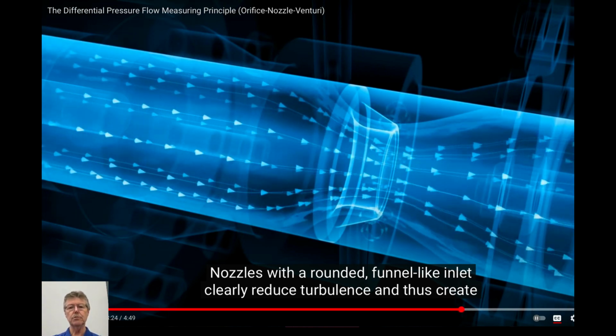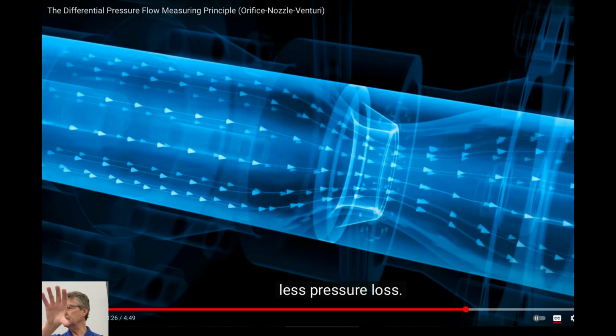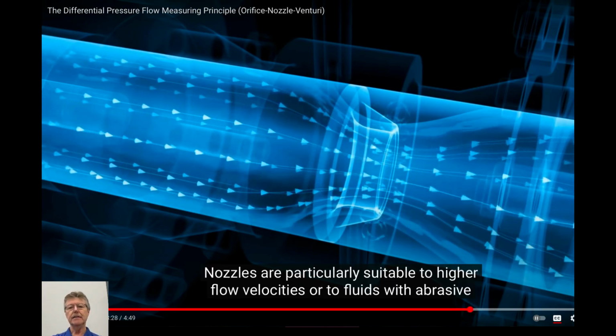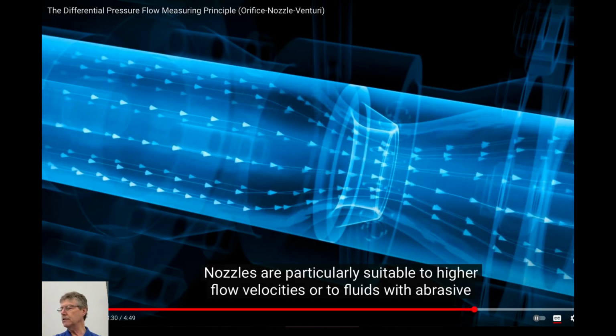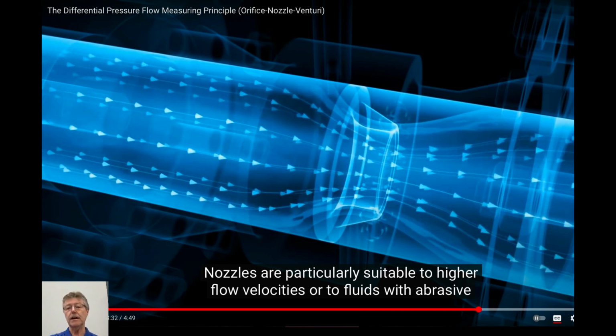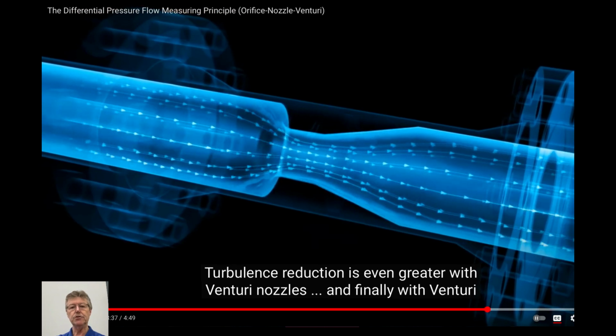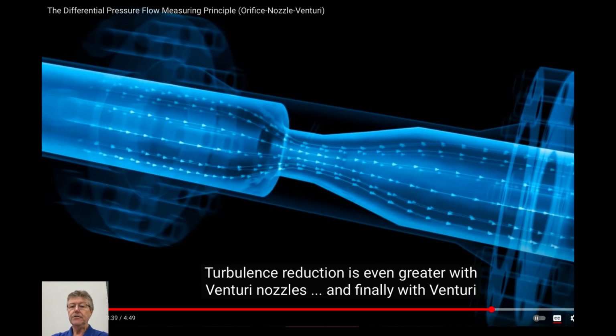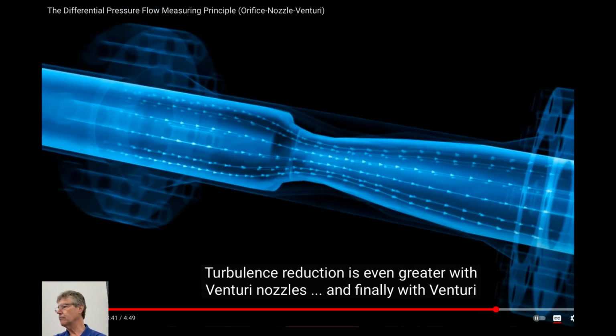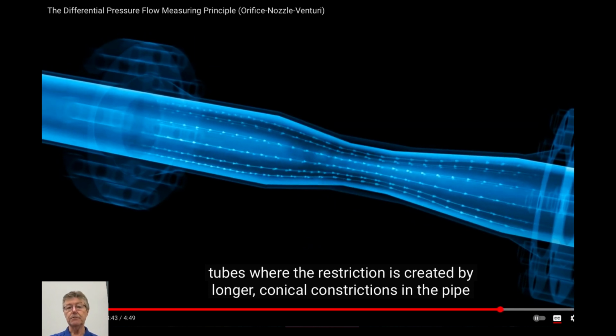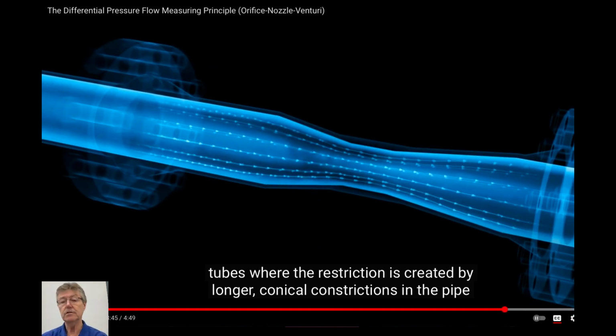I'm sure they'll show us a true one where the waist of it necks down, and there is a gradual change in cross-sectional area. So a gradual change in velocity. This is it here. So a Venturi flume would look like this, and you can get the most accurate readings of the velocity from that. So that's how you do it.